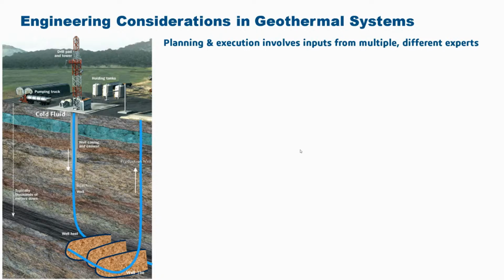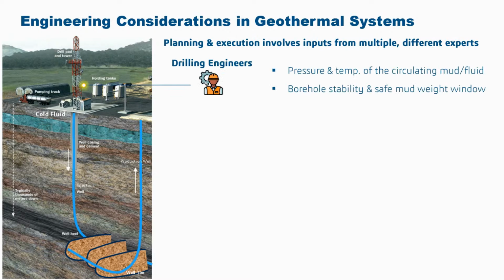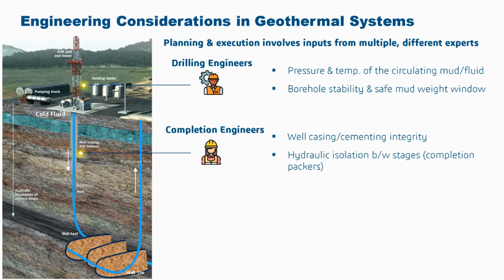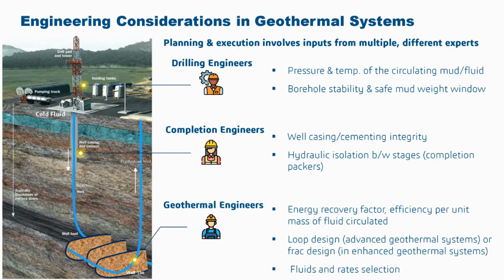So what are the various engineering considerations in design and execution of geothermal wells? Typically planning and execution involves inputs from multiple different experts. You need drilling engineers, completion engineers, and geothermal engineers. Drilling engineers are responsible for the drilling operation. They're concerned with pressure and temperature of the circulating mud or the fluid. They ensure borehole stability and safe mud weight window.